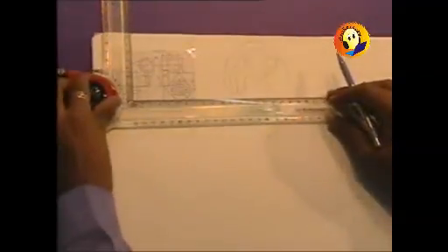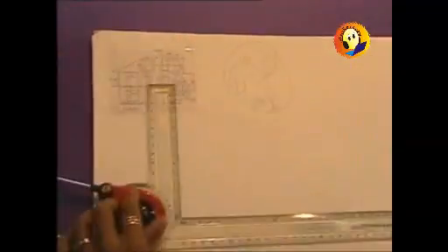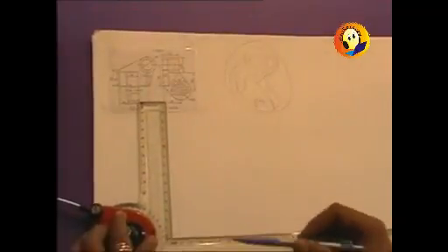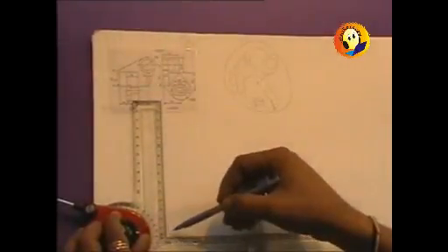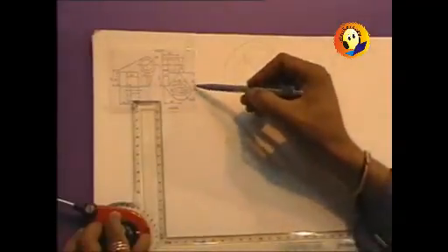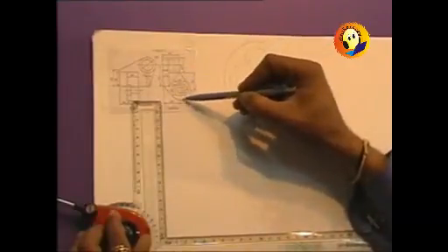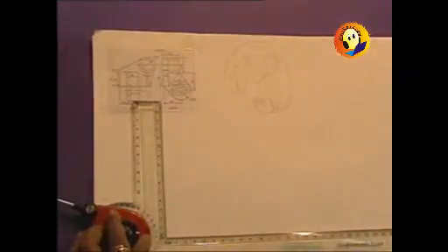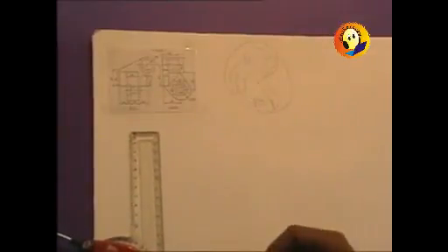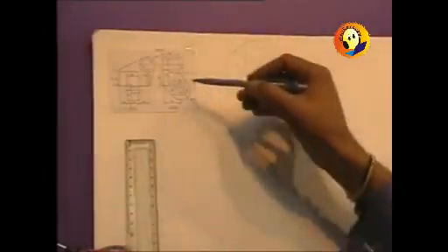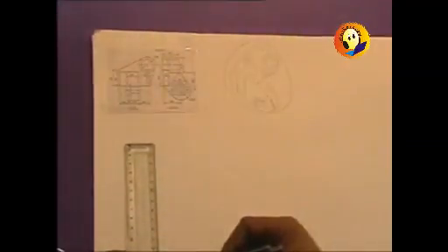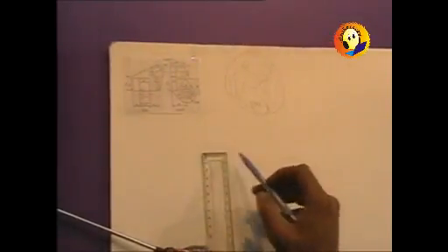Over here, which is our usual procedure of starting with a horizontal line, you can first of all find out what the height is. It is 50 millimeters, then 50, and this radius is 28. So another 28, 128 will be the total height. So let us shift that horizontal line slightly below, because otherwise we will enter into some other figure which we have already drawn. So start with the horizontal line and of course a corresponding vertical line.